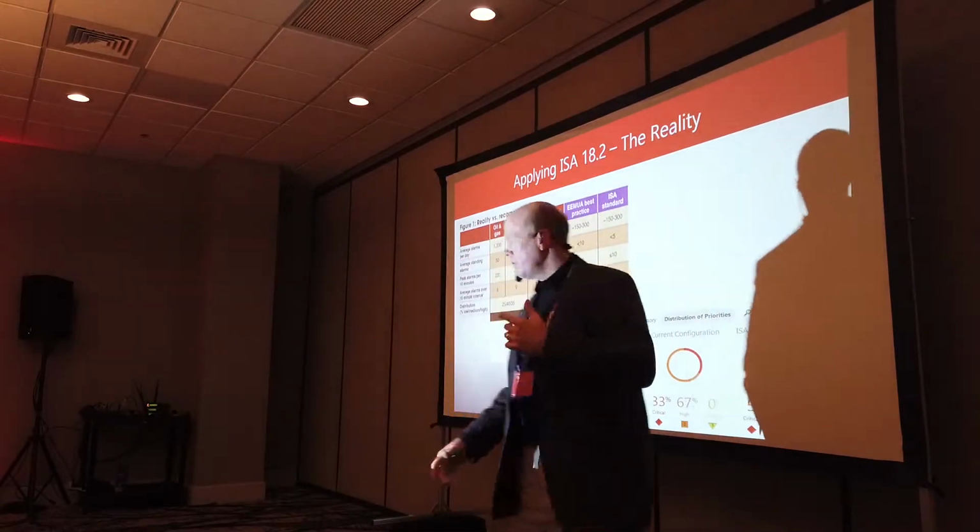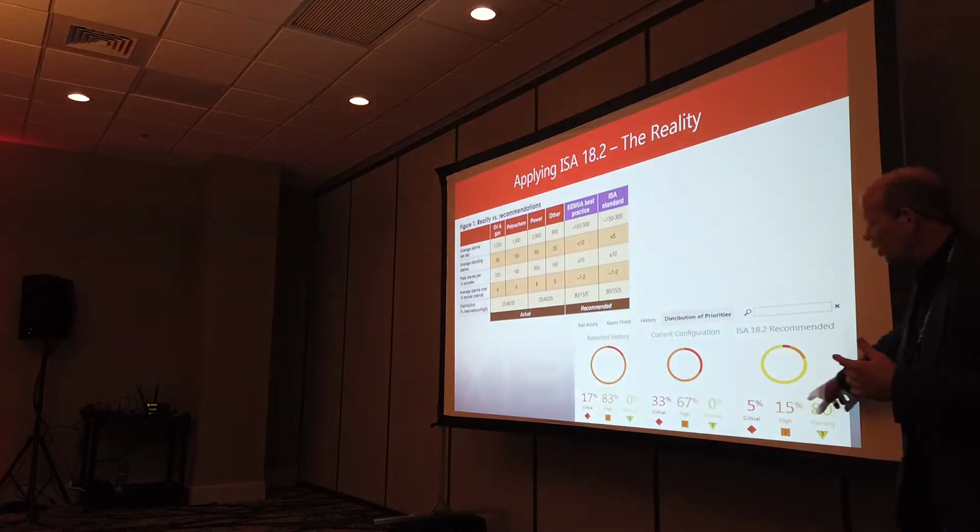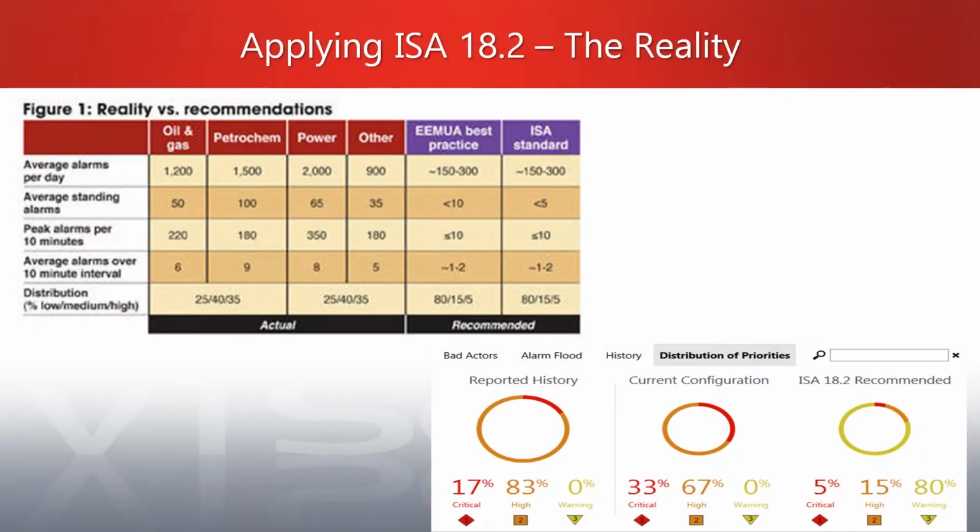What they came out with was a recommendation of what kind of alarms and the percentages. And maybe it's too low for some of you guys to look at. But what it says is they recommend no more than 5% of your alarms to be in the critical nature, being you've got to do something right now. That's critical. No more than 5%. No more than 15% are high alarms. Like you really got to look at doing something pretty quickly here, but it's not critical yet. And then 80% being warning alarms. Okay, put these things in your to-do list and go take a look at all that.